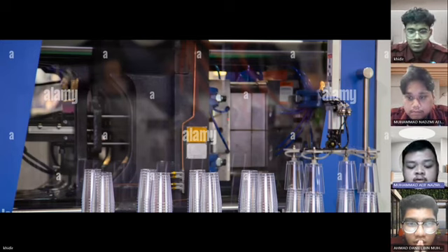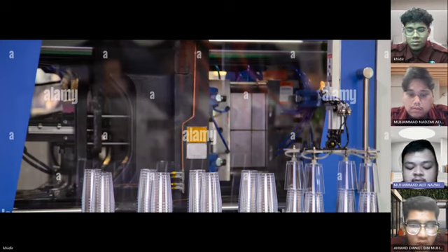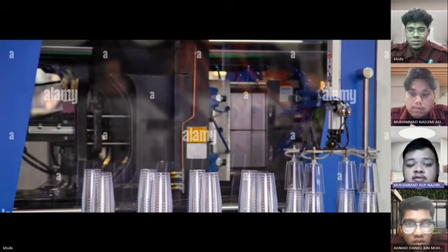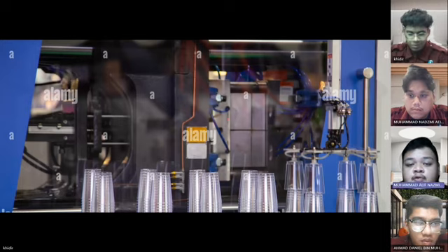And then any excess material is called flash. We're going to trim the excess from the part and make sure the part is inspected for defects such as warping, cracking, or inconsistent dimensions. We need to consider that our defective product is rejected, and we need to do it again from the beginning until we get a perfect shape without defects. And that's the flow.